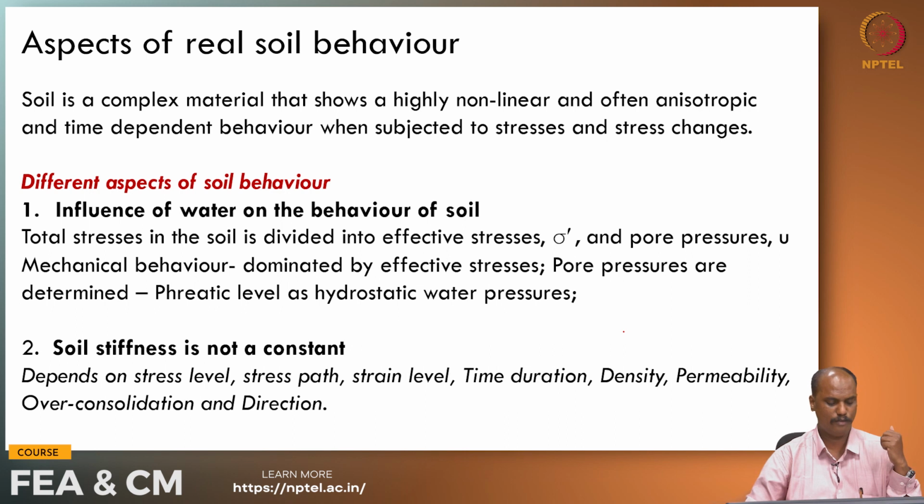And most importantly, if you observe, the soil stiffness is not at all a constant. It depends on the stress level, stress path, strain level, time duration, density, permeability, over consolidation, and most importantly the direction. As I said before, the stress level keeps changing with respect to time, and hence the soil stiffness also changes with respect to time.